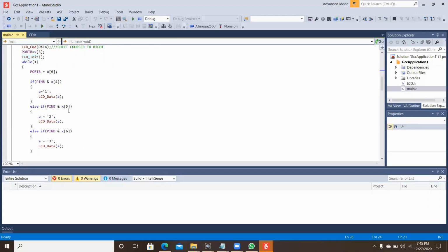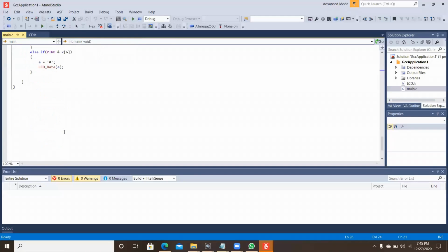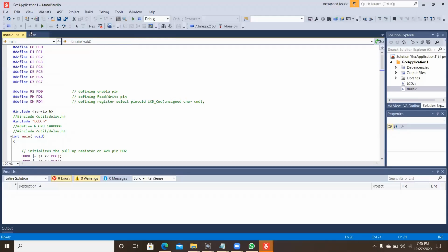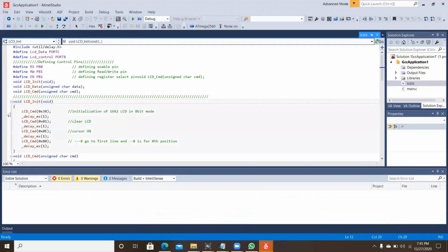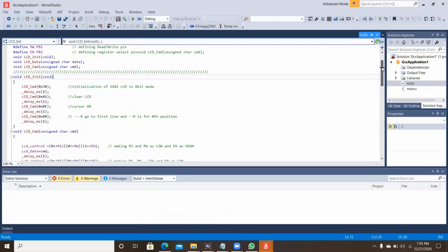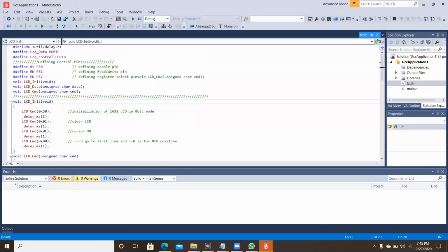These are interconnected with the rows and columns of the hex keypad, which is already written in our code, and there is also another code which is used to show the sentence hello world on the display of the LCD, which is written like this, where the RS, RW and enable pins are connected with port B, PB0, PB1, PB2, and these are the header files and functions.